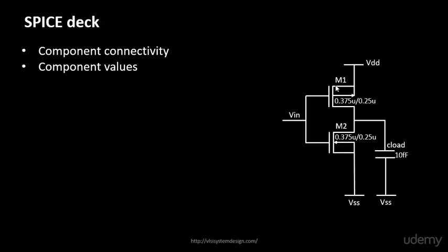But there are again reasons and there are applications for both of them. You need this kind of inverter, as well as an inverter which has a PMOS bigger in size. You need both kinds of inverters for your application. So we'll get into those in a bit. For now we'll just look into the PMOS and the NMOS of the same size, and see what happens to the characteristics.